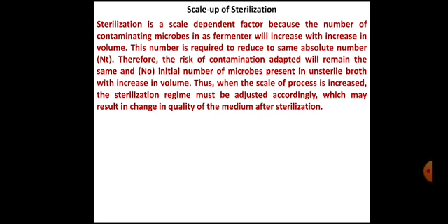For this, you need to recall the formula and definition of the Del factor, and the meanings of Nt, N0, and the value of N0. One example of calculating the holding time while designing the process of batch sterilization we have already learned. You just go through that part, then we can come back to see how exactly the Del factor is useful for the scale up of sterilization.